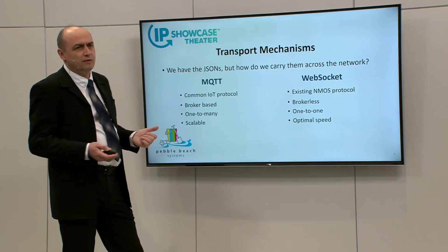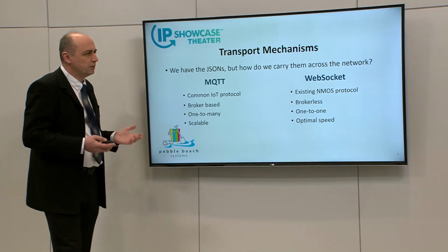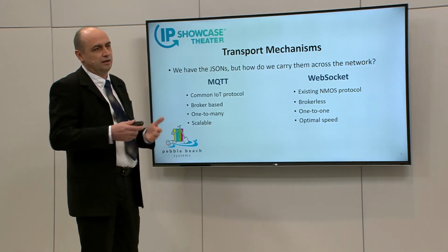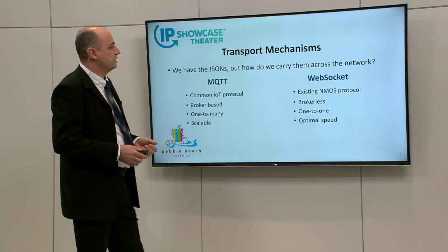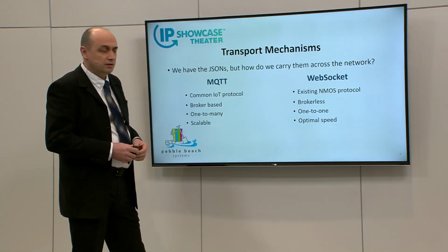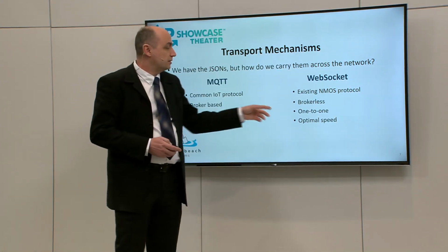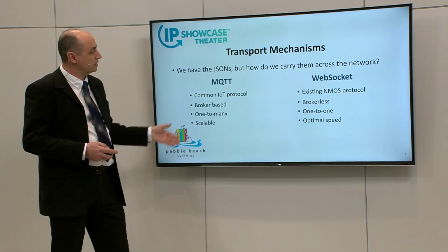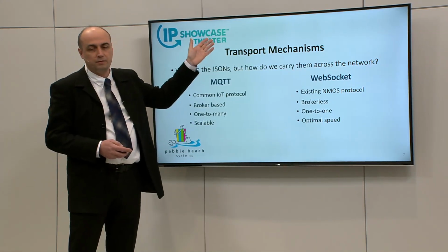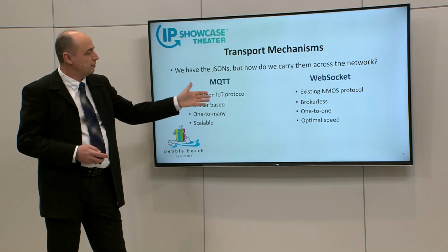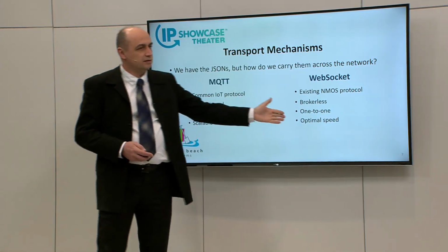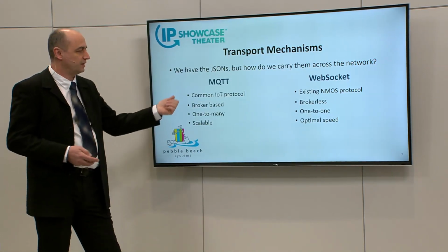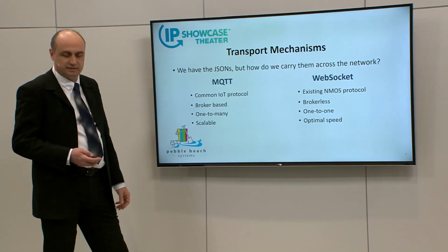But also, if you know that in your facility you will be mostly connecting devices one-to-one anyway, and you won't have many one-to-many connections, WebSockets might be the optimal choice because they are direct. So there is no broker there. Because if you use MQTT, there would be one connection to the broker, there would be the broker queue, and there would be the connection back to the receiver. In this case, this is one-on-one, so it will probably be at least twice as fast as MQTT, which could be critical in some use cases.